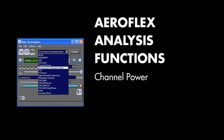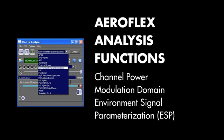Channel power, which measures the total power through an arbitrary channel filter designed by the user. That data can be sent to a strip chart to be monitored for changes over time. Modulation domain is another very popular function. It can be used to calculate and plot the AM, FM, and PM waveforms of the signal data. ESP can be used to detect parameters of the signal present in an environment. We'll take a look at this analysis function next.